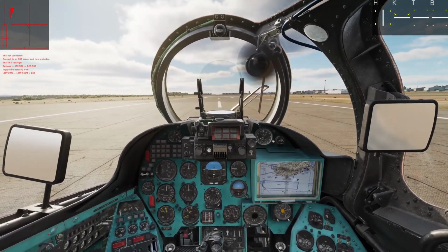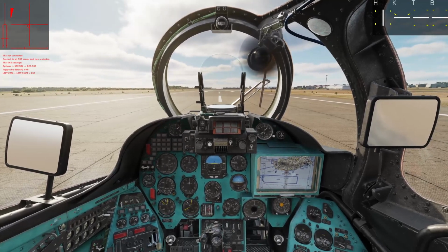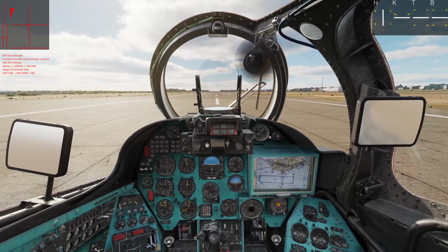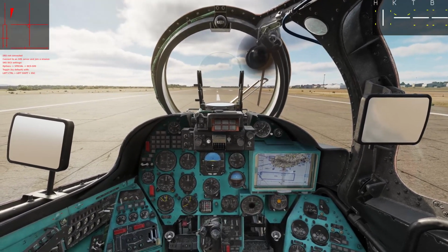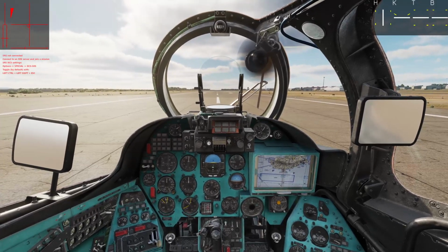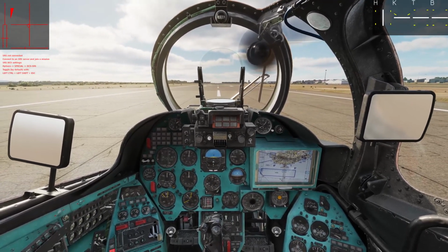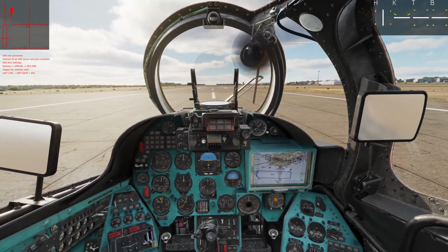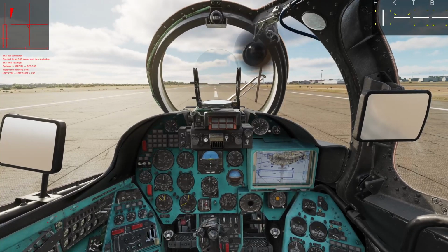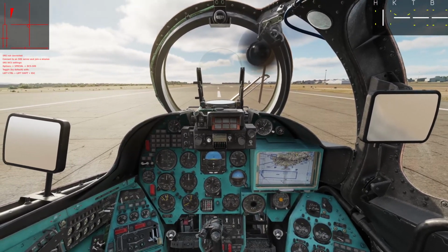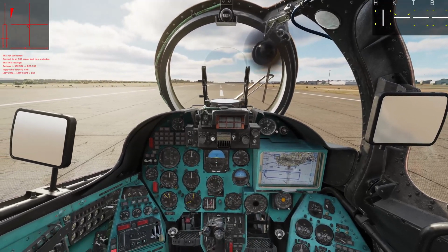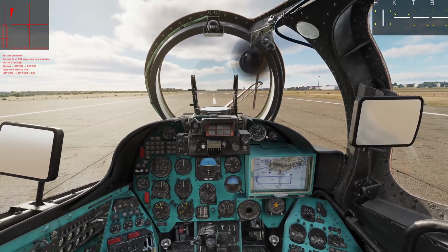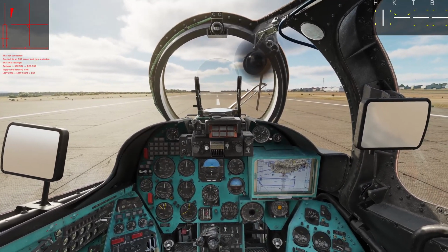Now, just some basics and things that I may expect to see in left side flight. For a helicopter like the Mi-24, the rotor that spins clockwise when viewed from above, flying to the left, in a perfect left side flight condition, puts the tail rotor in a climb condition, which means you require more power from the tail rotor. But it's a nice, clean configuration. You shouldn't expect any kind of weirdness, and indeed that is what we see in the simulation.